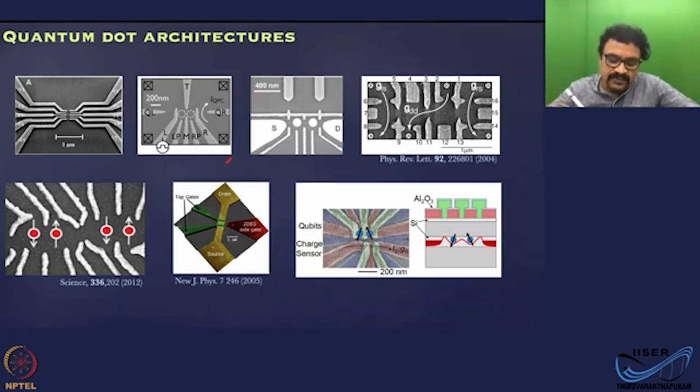Okay, so now you need a readout device integrated to the system. For example, a quantum point contact or a quantum dot. Let's say the quantum dot is a single electron transistor. So if you look at here, this is a lot more compact. So you have source and drain and 2 quantum dots, and you have a readout device on the other side. Either this one or this one you can use to read out. This is a slightly different kind of design compared to this, but conceptually they are the same. You have 2 dots and you have 2 sensors.